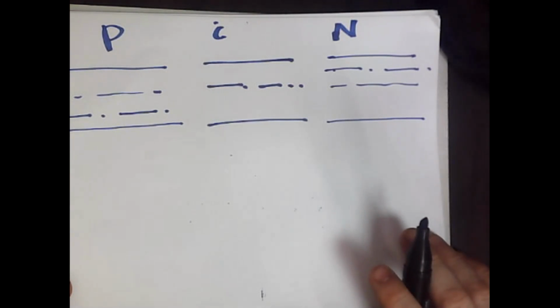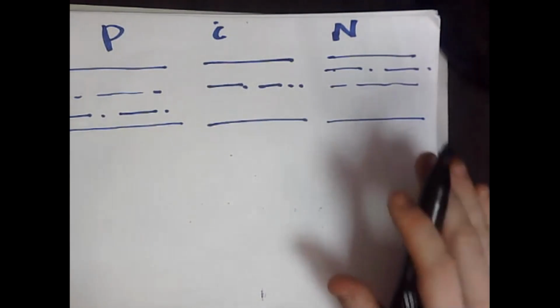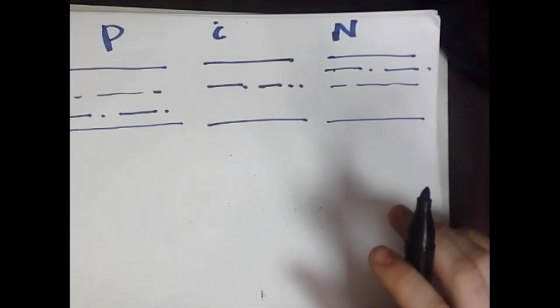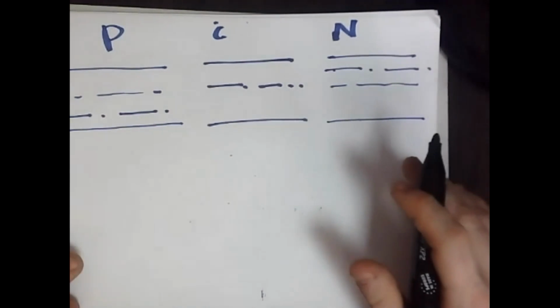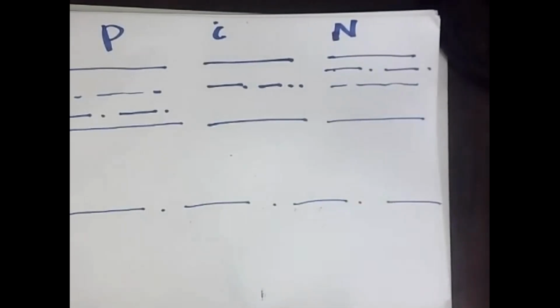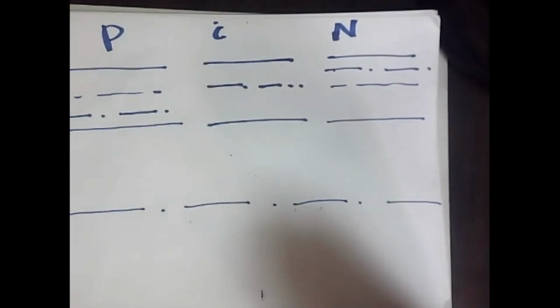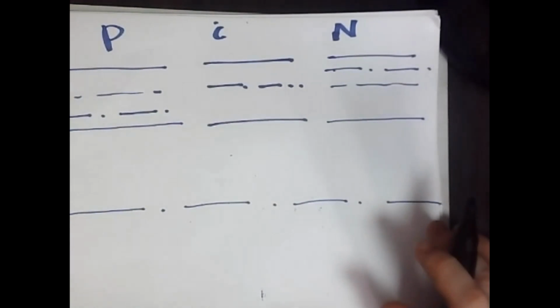The second step is that we merge all these regions together, and our reference under thermodynamic equilibrium is the Fermi level, so the Fermi level should be constant. Then we plot everything with respect to this Fermi level.